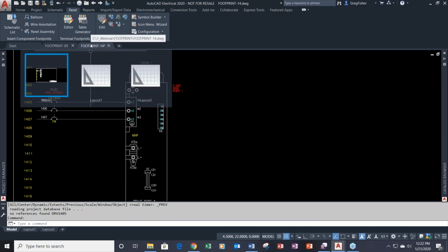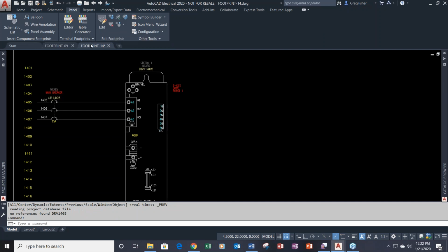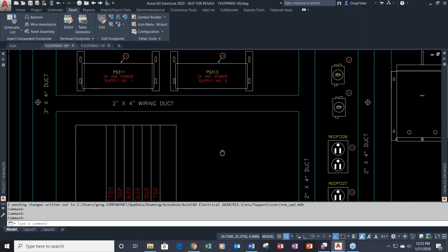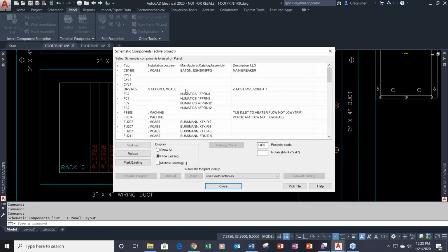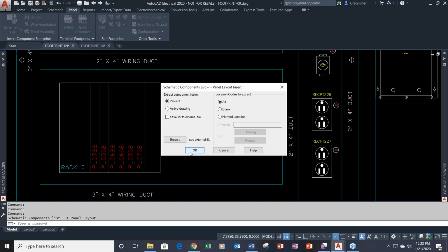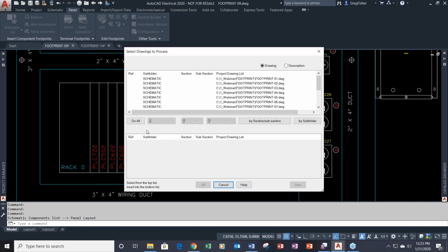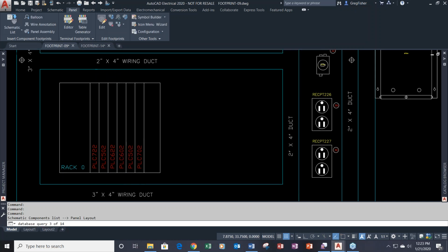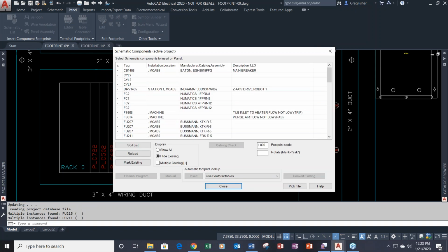Now when I go back to the panel, let's say I'll go back to my schematic list, pan down to here. So right now, as you know, I'm just going to reload this. I've created a schematic symbol for this new component. I've just added the part record to the parts database. Haven't created the footprint symbol yet. There's the part number right there.